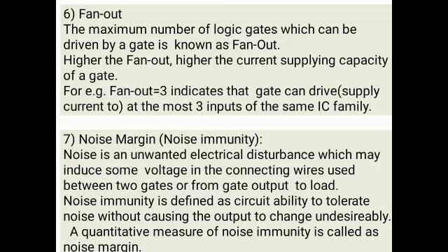If fan out is 4, means we can connect at the output of a gate 4 inputs. Means it can drive 4 inputs, but they should be of the same IC family, that is, they should be of TTL family, all of TTL family.